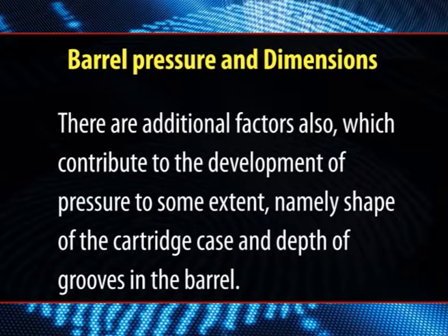There are additional factors also which contribute to the development of pressure to some extent, namely shape of the cartridge case and depth of grooves in the barrel. For the same quantity of powder, greater pressure will be developed if there is an abrupt junction between the neck and the case.